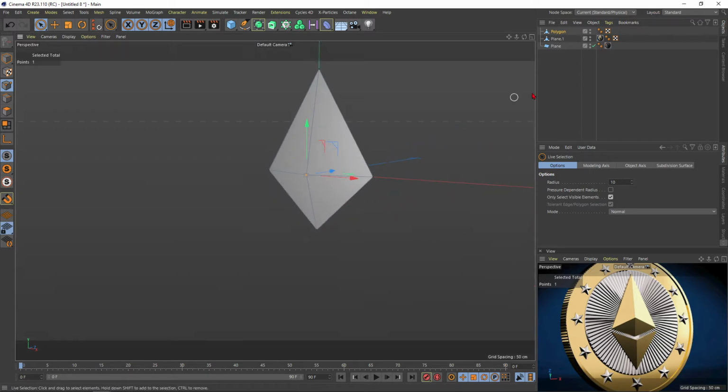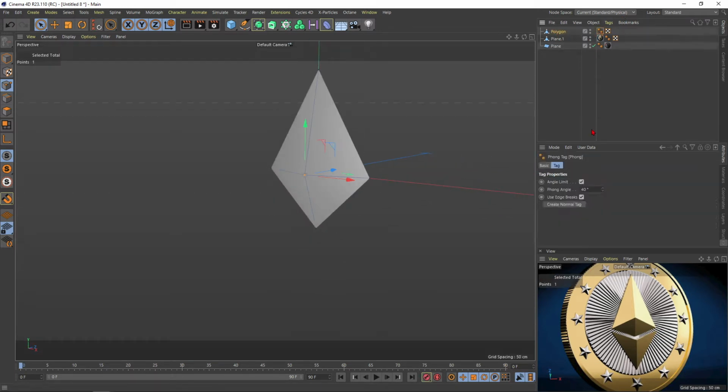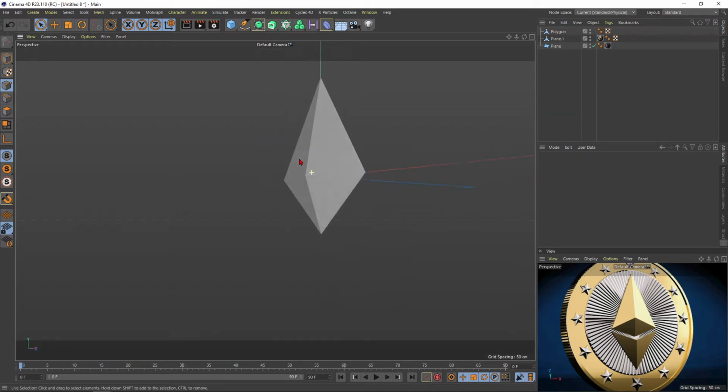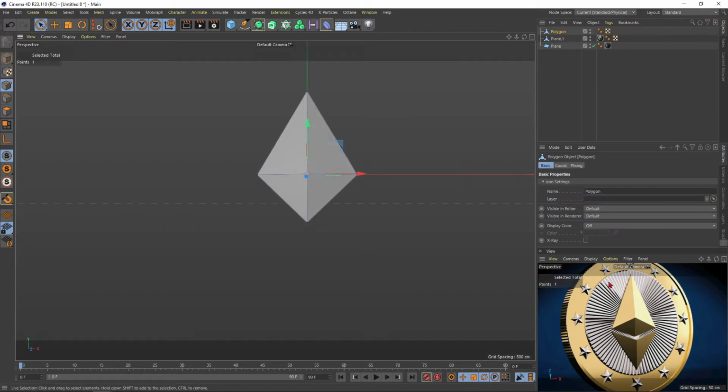We have some crazy shading here, so that looks like it's round, but that's not really the case. So let's go into the object and put this one, for example, to 10. Now we reduce the Phong breaking and we can see the angle. Okay, so that seems to be okay, but it looks like the angle is going up here. So we need to put this one up.